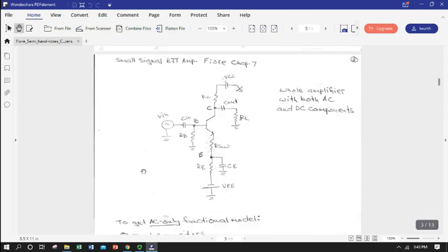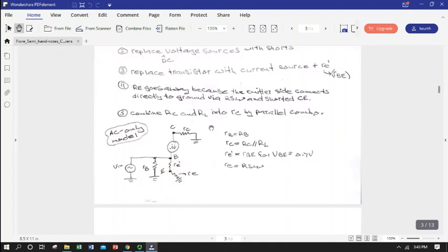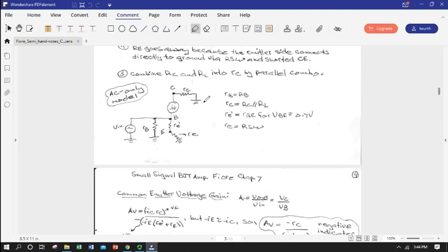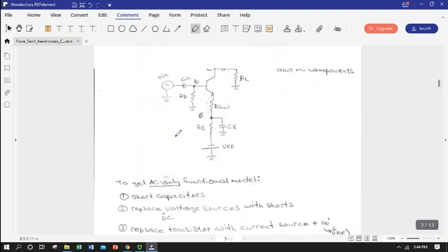So this whole schematic from the standpoint of our AC signal becomes this. Much simpler. So I'll draw a few circles here. So here's where our BJT is. Basically this, everything in the red is our transistor. So here's our collector input, here's our AC current source, here's our base, and here's our little resistor, little RE, representing the resistance of our base emitter junction to an AC current.